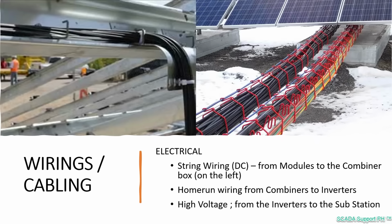By design, we are trying to minimize the amount of wire that we have within the array to minimize the resistance, as more resistance eventually leads to greater ohmic losses during operations. Wires coming off of the inverters to the substation we consider as high voltage.